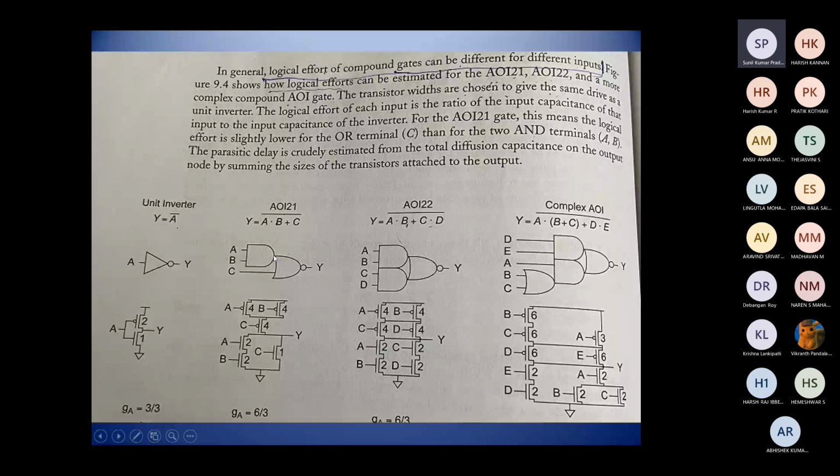It's shown here. Okay. So this is our two PMOS circuits. These two PMOS circuits are connected in parallel, and that is connected in series. And the overall A, B, C that we see here, because this is a three-input circuit, is connected to this NMOS circuit here. So two NMOS, A and B, are connected in series, and then these are connected in parallel with C. Okay, and finally we get the output like this.